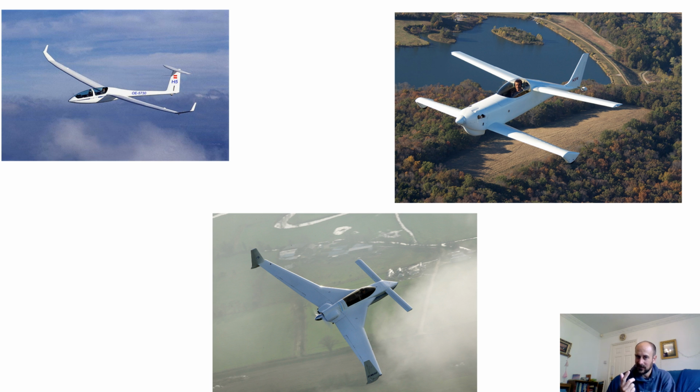In most cases, that's achieved by angling it at a higher angle to the main wing, or to the rearwards wing, I should say. That's not quite the only way it can be done. Also, tweaking wing sections do have an effect, but changing the angle is the most powerful way to change the lift coefficient. So in almost any stable aircraft, you will always find this feature that the front surface is at a higher angle of attack to the back surface.